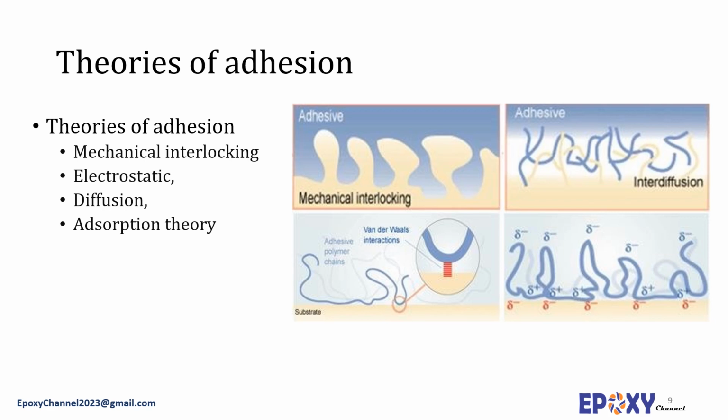It should be mentioned that all intermolecular forces are very short-range and need proximity to act. Moreover, all substrates, even the most polished ones, are still exceedingly rough. Therefore, only a very small portion of the surface is in true intermolecular contact, unless the adhesive has the ability to flow and achieve contact with the majority of the substrate surface. This indicates the importance of wetting in achieving a good adhesion and a high load bearing capacity.